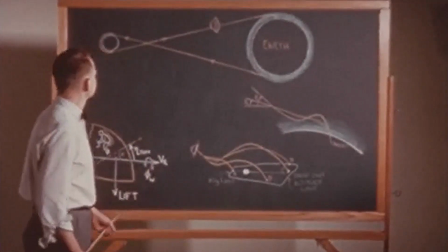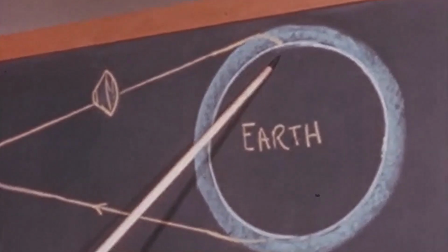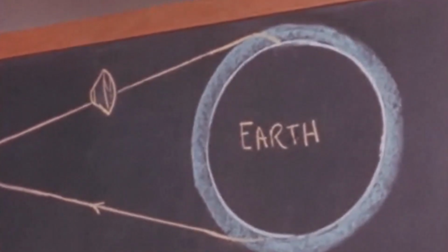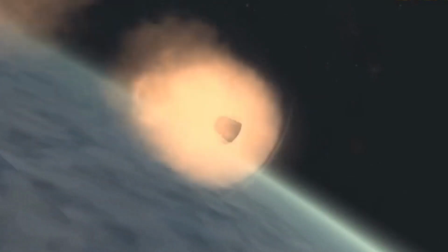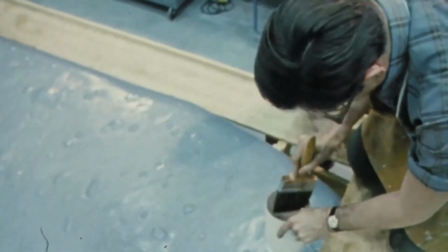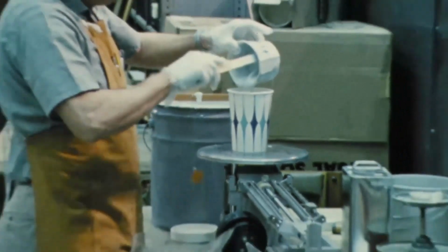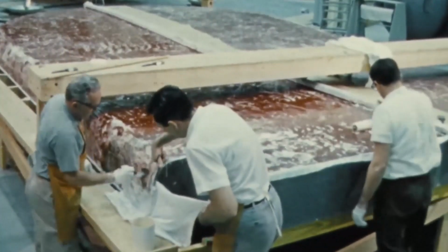As the capsule begins to encounter the atmosphere at about 62 miles, the friction buildup causes a massive increase in temperature of up to 1700 C on the protective heat shield. Most metals and alloys would simply melt or be destroyed at such a high temperature. To solve this problem, the underside of the capsule is coated with a material known as an ablator. These materials can absorb and then radiate large amounts of heat for brief periods while they too are slowly destroyed. Ablators can be made out of a variety of materials, including phenolic resins, epoxy compounds, and silicone rubbers. You may well have silicone handles on your kitchen cookware and utensils.